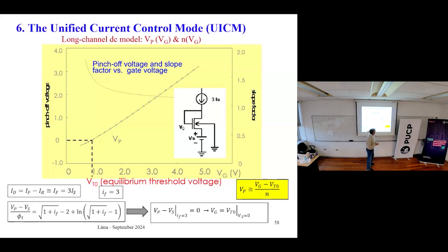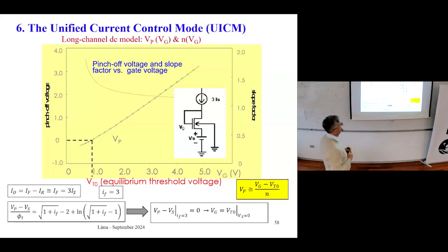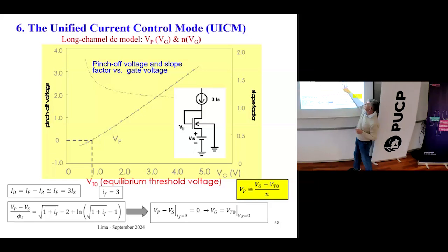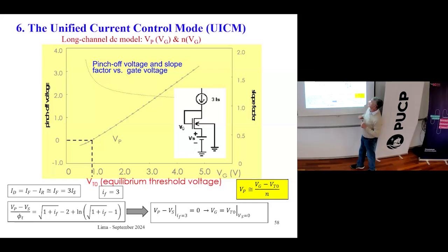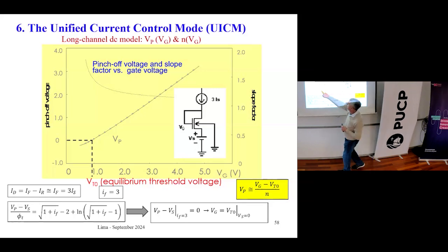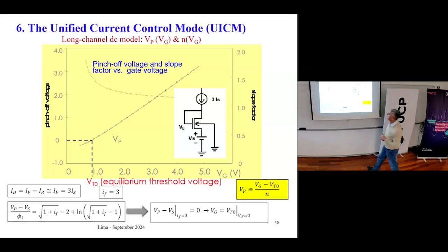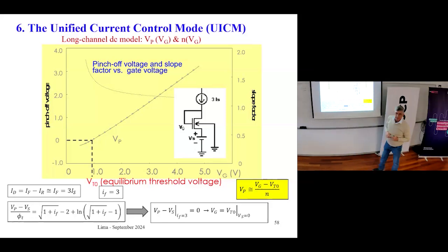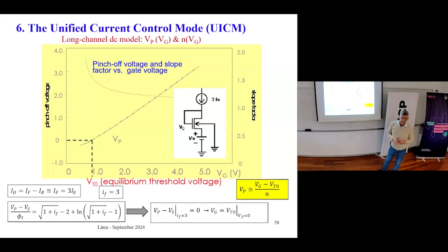And then you connect your transistor, connecting the drain to the gate. Then you connect the source to a DC voltage source. Now you change the source voltage, and you measure the gate voltage. So this axis is the gate voltage, and this axis is the source voltage. In this case, the source voltage equals the gate voltage.